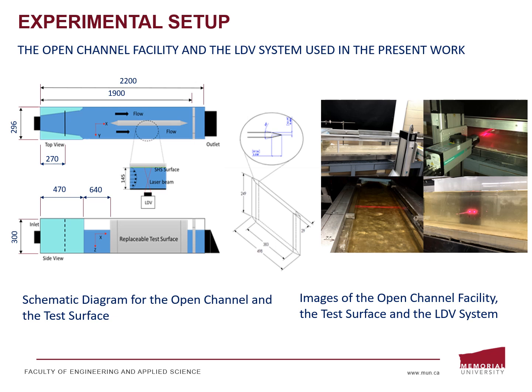145 millimeters. The flows were seeded with particles of silver-coated hollow ceramic spheres of 10 micrometers diameter to capture the near wall region details. One operating condition at an approaching Reynolds number of 34,200 was selected for all tested surfaces, and the two-dimensional laser Doppler velocimeter has a three-dimensional traverse mechanism for flow field mapping over the test surface in many positions and is adjusted to move for 20 points near the wall with a 1 millimeter step, then 5 millimeter step for the rest of